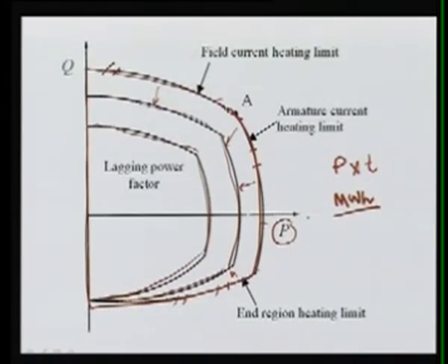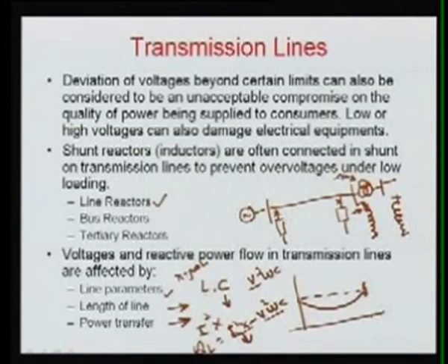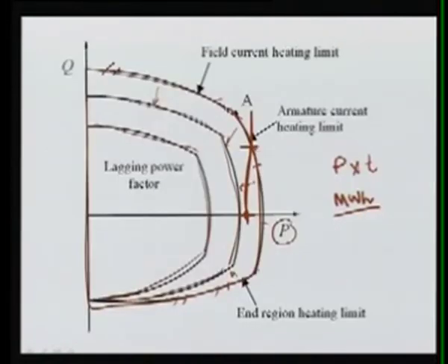For the reactive power of the generators, normally they are not paid, but in the competitive power market we presently have, we are now also going to give payment for reactive power generation. Now you can see a generator which is generating real power, let us suppose at this value. It can generate reactive power from here up to this value. If this is the real power generation of your generator, you can generate reactive power within this limit.